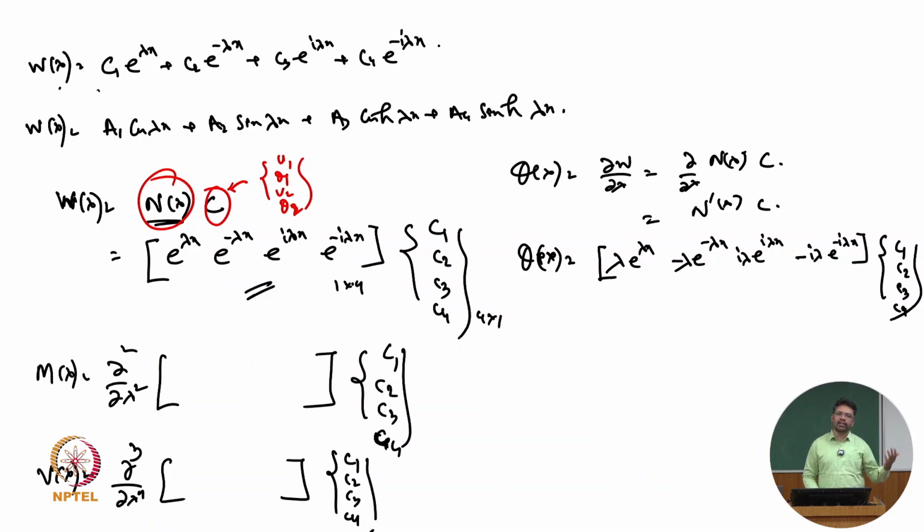In the normal finite element case, when we write it in terms of the degrees of freedom, we try to assume some displacement profiles, and accordingly we write the shape functions and solve it. But here the shape functions are, first of all, frequency dependent, and they are the exact solution of the governing differential equation. That is the important point. Perfect. Any doubt?